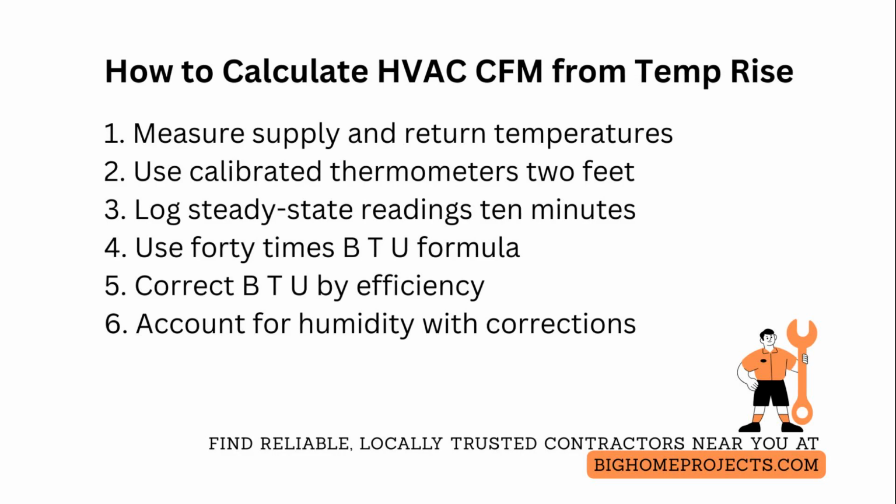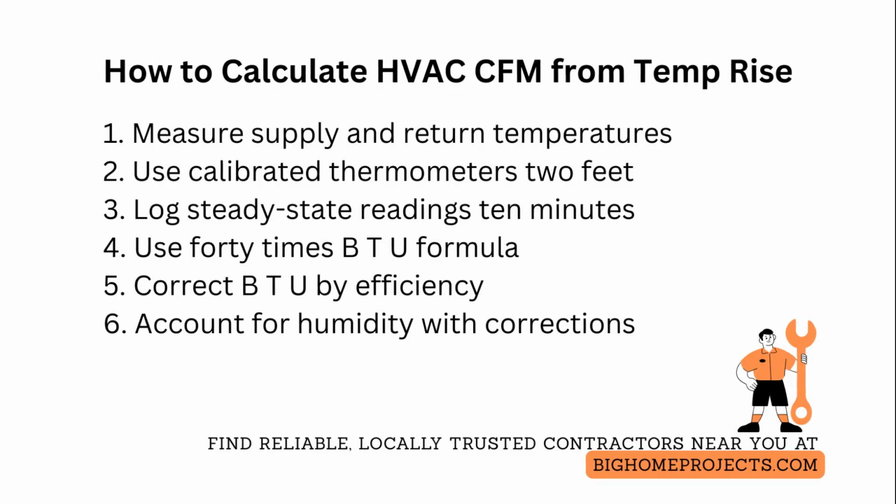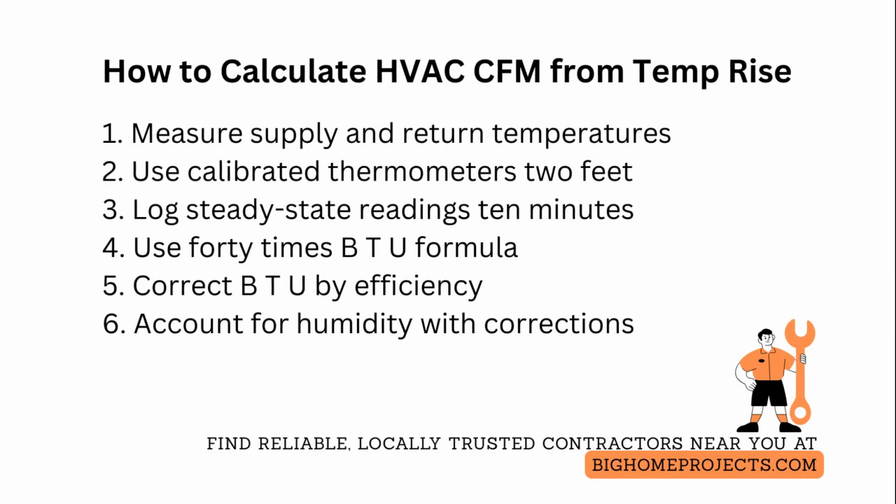When measuring temperature rise, account for wet bulb and dry bulb differences in high humidity environments because latent load changes apparent rise. Apply a correction factor or measure enthalpy if the system also conditions humidity.